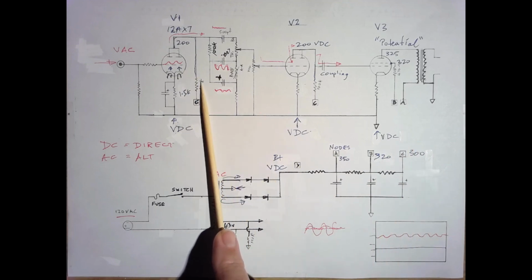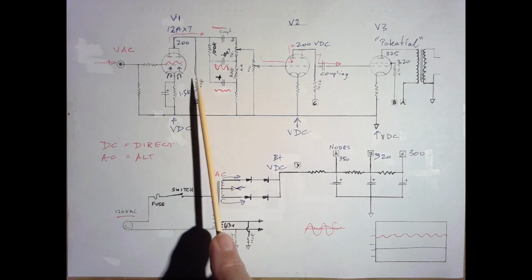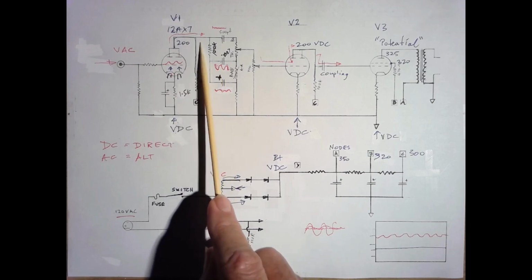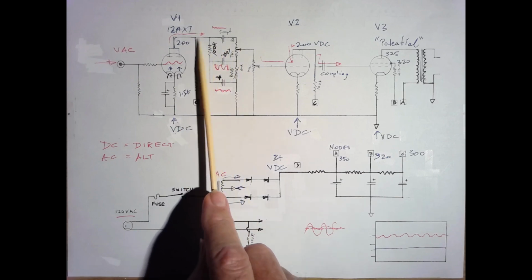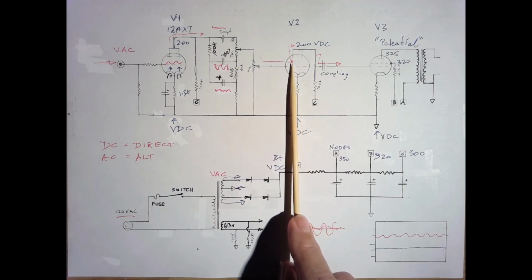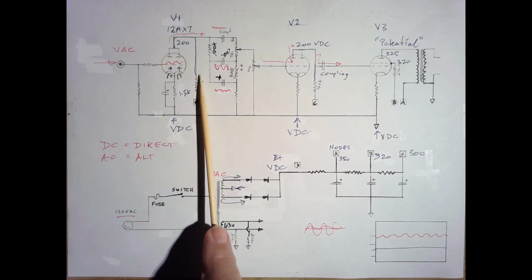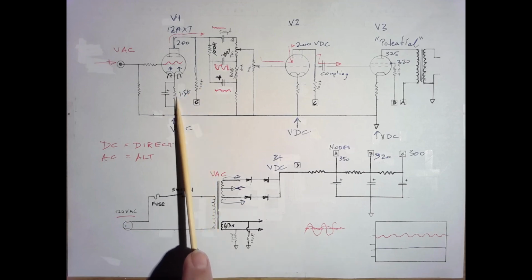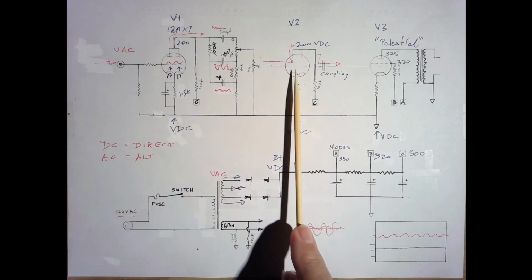So what we tend to see on a high gain stage preamp is that if we have a larger than usual plate resistor, say 200 or 220K, we will have less voltage here on the plate, but the resistor will resist much more of the AC current. It'll stop any signal, it'll force all the signal to keep going this direction, it won't let anything past. So it'll come over here and overdrive this stage. So it's interesting when we talk about biasing a tube with the load resistor and the cathode resistor, we're getting more signal out of it, but that actually overdrives the next stage.